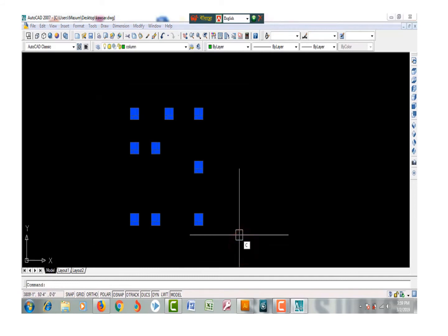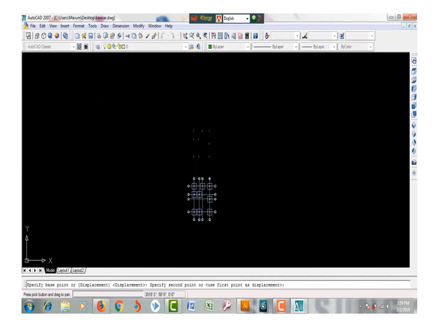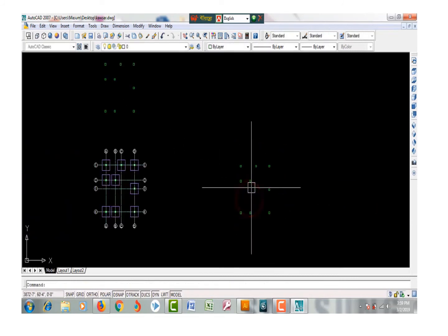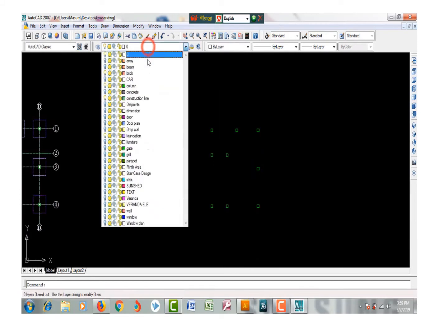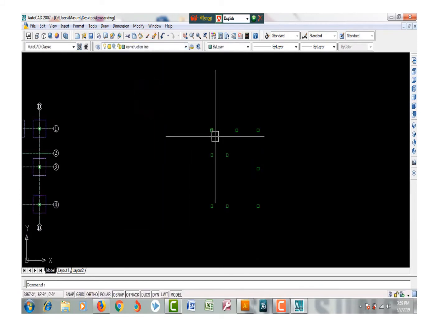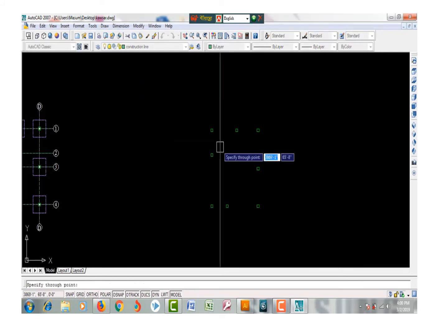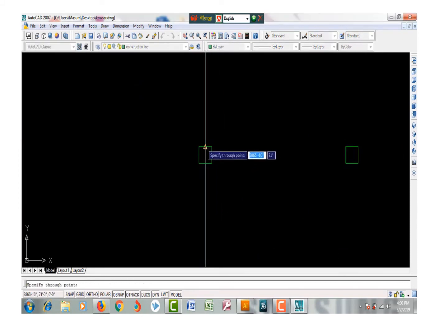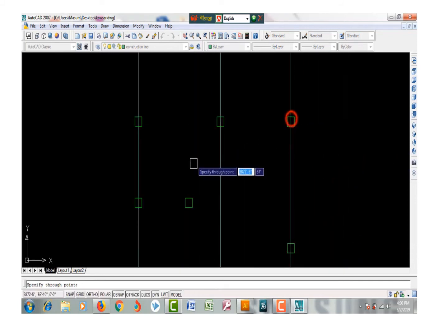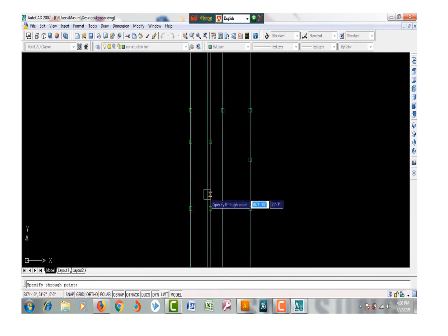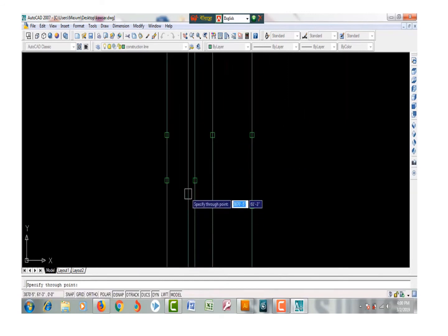As a design engineer, we can rearrange the columns depending upon the structural performance also. So this is the column arrangement that is given. Then with this we are supposed to develop the footing arrangements, that is footing layouts, then excavation marks. Before that, let us plot grid lines for the given columns so that I can understand this. I am constructing a construction line in both the longitudinal, that is both the x-axis as well as the y-axis, to specify the grid numbers.